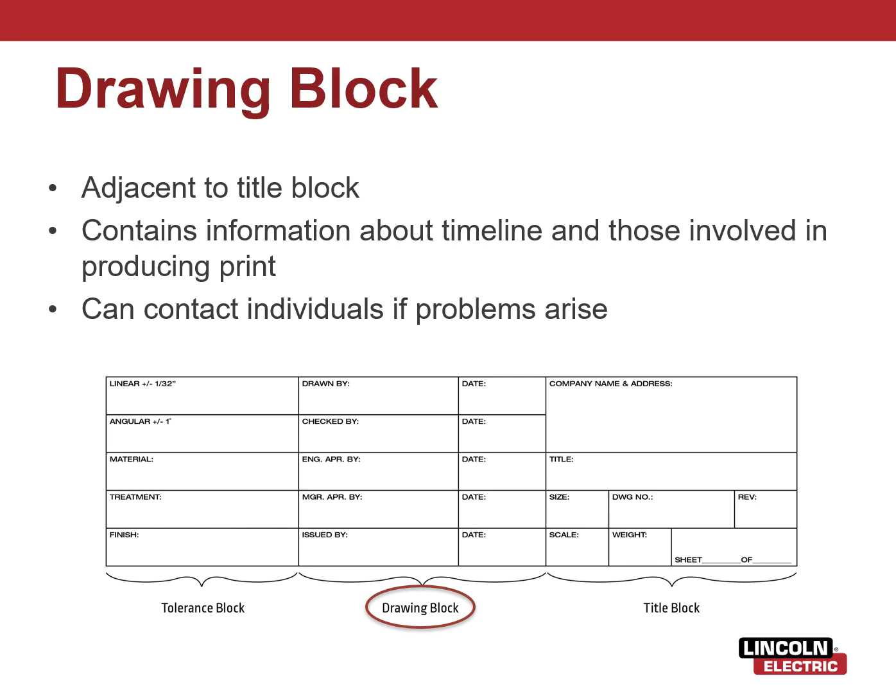So it's going to have the person who is drawing it. This could just be some paid intern or whatever. You're just the one that's in SolidWorks or Onshape or AutoCAD. You're the guy that drew it, and the date. Then who it was checked by, maybe your team lead, and the date they checked it, and then the date that the engineer approved it. So when the engineer looked at it, it was all good. He signs off on it, and the date they signed off.